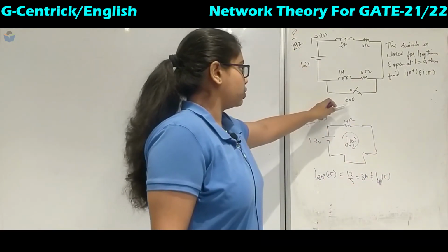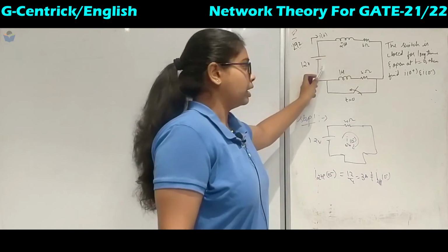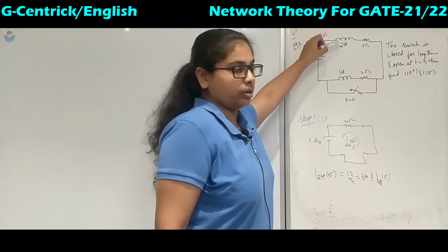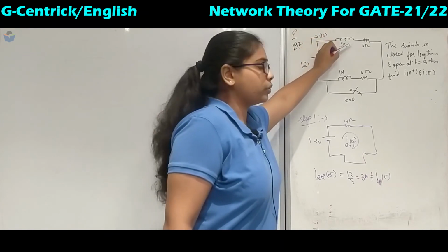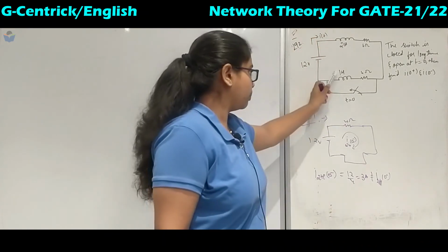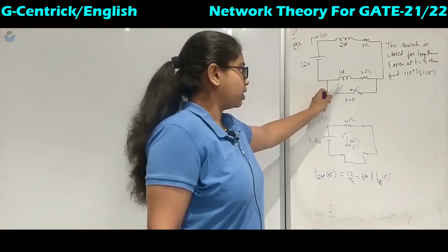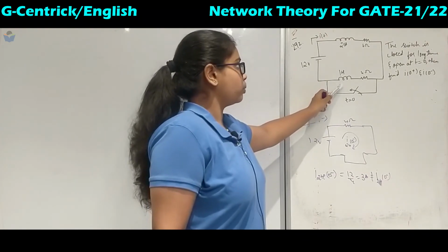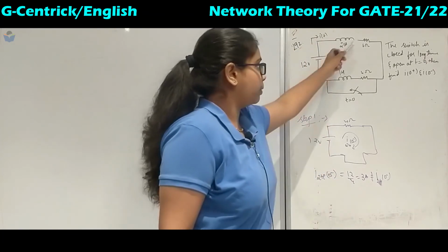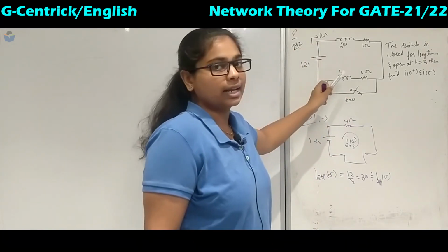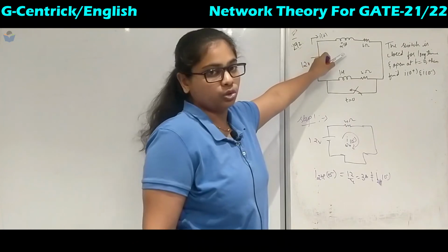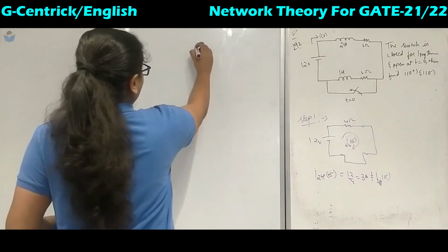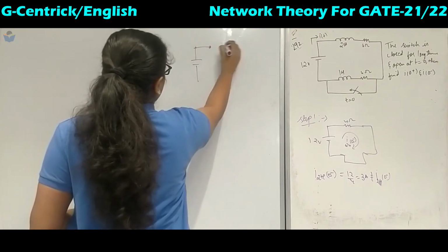Why? When the switch is open, everything will be with the source. Now this will be replaced with an open circuit inductor and the current source of 3 ampere. Since initially the other inductor was not charged, it will also be open circuit. When it is open circuit, the 3 ampere which should flow will not get a return path to this source. That is why the KCL will fail. If you just draw this for some time, it is like this.